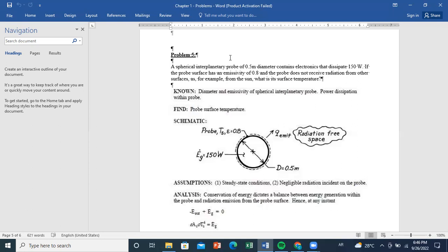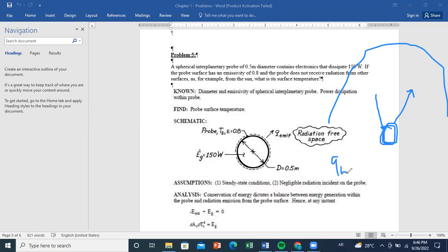If you remember in the course material, when we introduced radiation, we said that a surface will absorb and will emit heat by radiation. We considered that we have an infinite surface surrounding the object, then the net radiative flux will be Q net equals epsilon times sigma times area of the surface times T surface to the power 4 minus T infinity to the power 4.